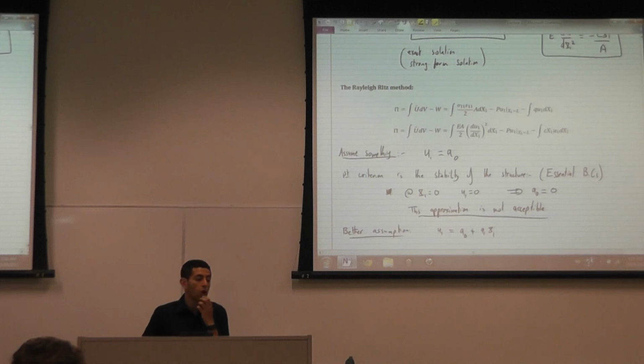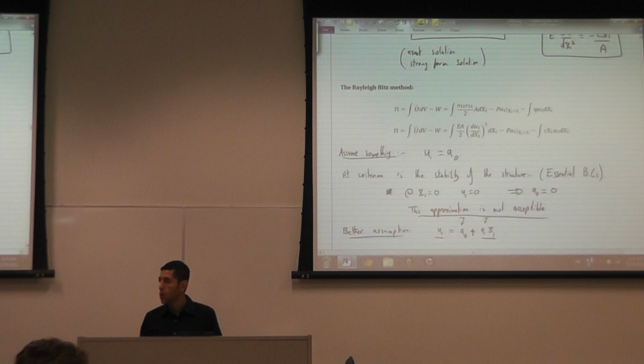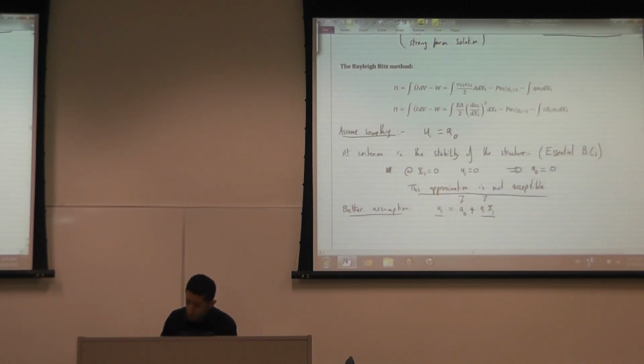They have to allow all the possible strain forms, all the possible lower strain forms. So any displacement function has to allow rigid body displacement, linear displacement, and so on. If it allows linear displacement, it has to allow rigid body displacement, or what we call constant displacements.